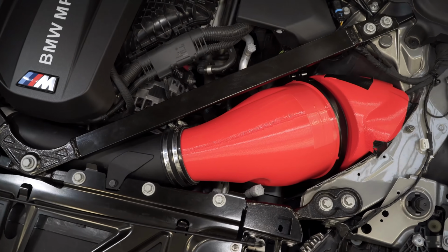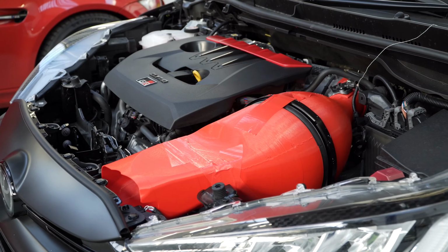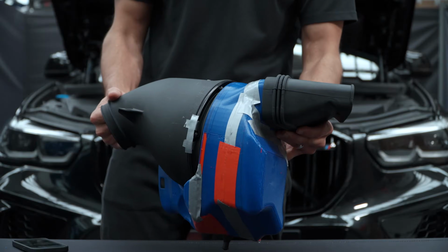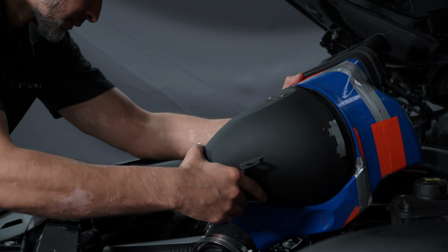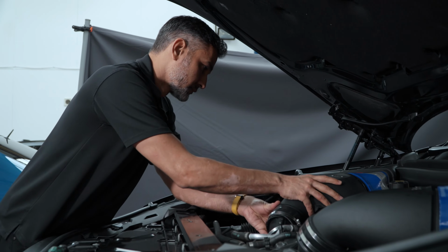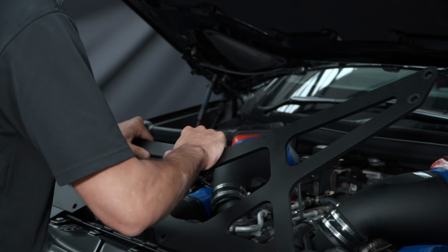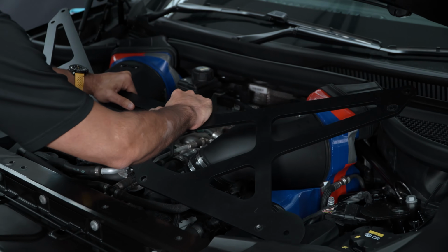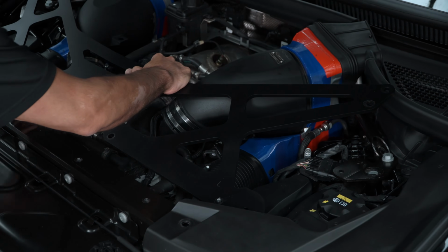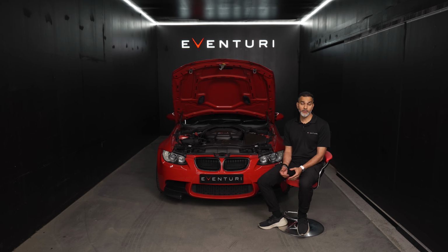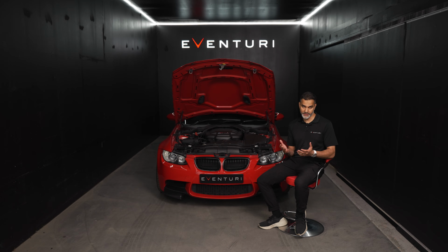The 3D printed prototypes are then test fitted in the car, which gives us a very accurate way of checking our design in terms of its fit, and also for any clearance issues, things we may have missed in the scan, and to also give us a way to see how the intake looks aesthetically in the engine bay. Once we're happy with the fitment of the 3D printed prototypes, we can take those and go into real-world testing.